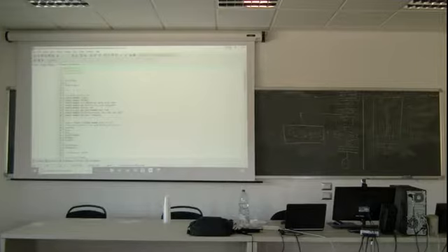So can we assume here that in 1 centimeter we have the same velocity? No. Because we have something physical, the boundary layer, stack effect, whatever. So there are huge gradients in 1 centimeter here. But here, can we assume 1 centimeter? Maybe yes. This particle of air has more or less the same velocity as this one. We can assume that here, but we cannot assume it there. That's why we need more nodes here than here. Do you follow me? Yes?